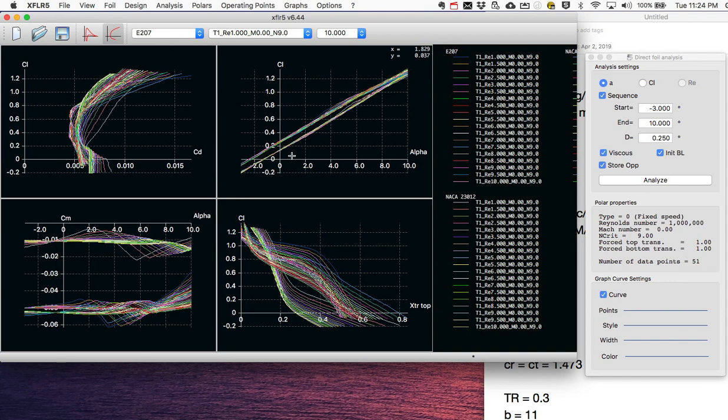Here we see that I'm looking at this, the Epler and the 2412 have very similar lift lines. I think their cambers are quite similar. Slightly lower camber for the 23012. Actually, no, I had that backwards. This is the 2412. This is the 23012 and the Epler.